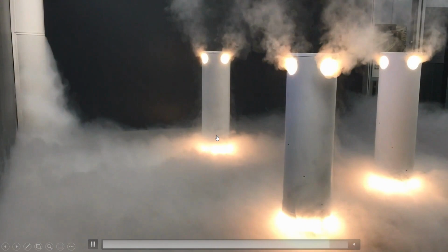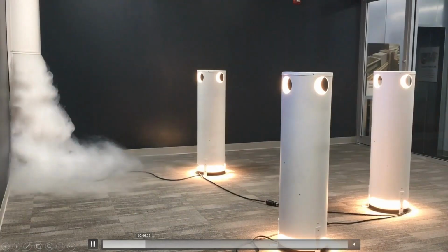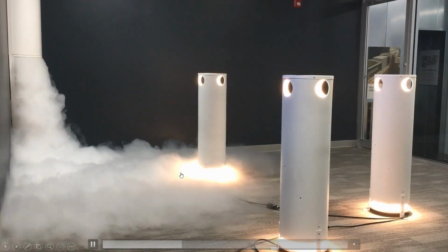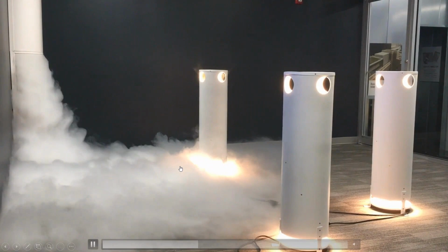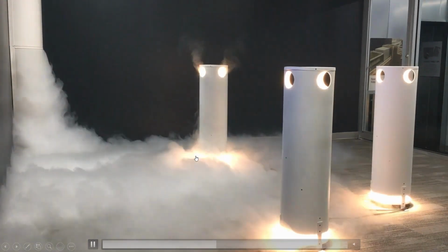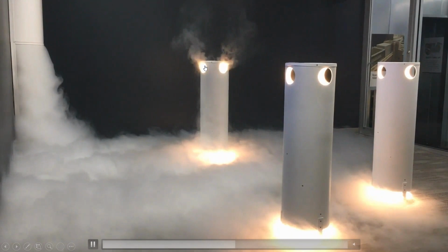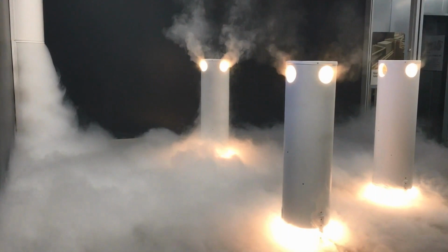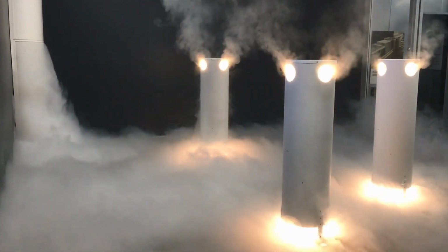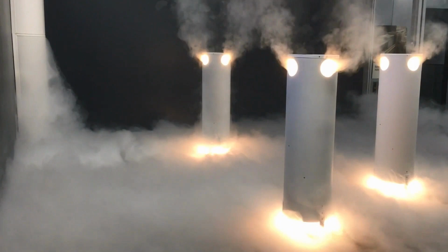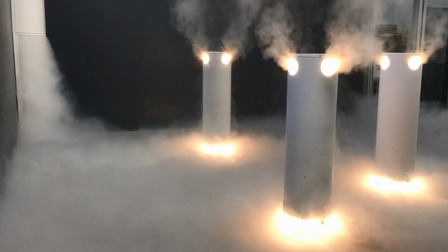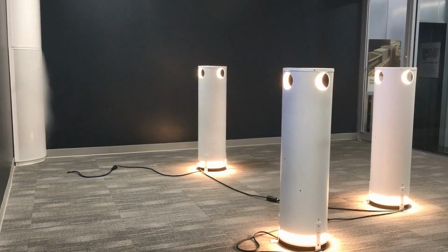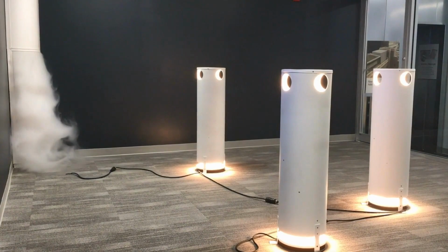And so I'll show you, I'll let that play once more here. Let me see if I can start. It's a little bit choppy, but you can probably see that the air is moving a foot or two quite slowly once you get away from the diffuser. In fact, with the thermal plumes, we're used to feeling a certain air velocity across our bodies. So what you find with these systems is a very flexible, comfortable system. The occupant on an individual level is actually driving the air movement throughout the space based on that particular person's heat output.